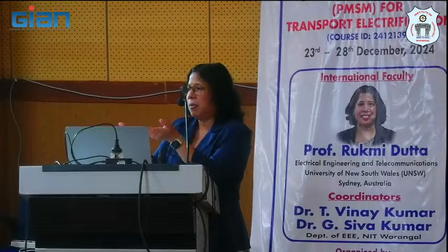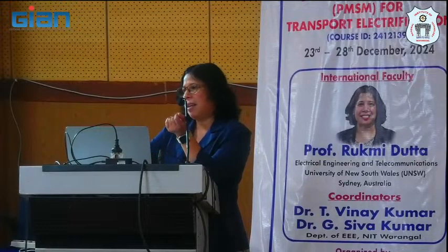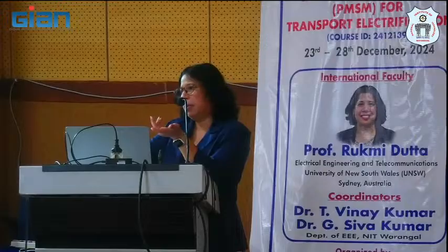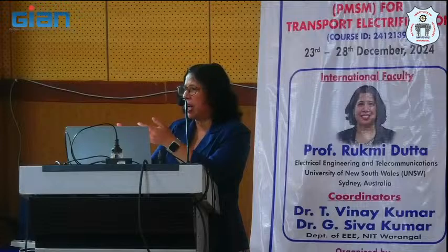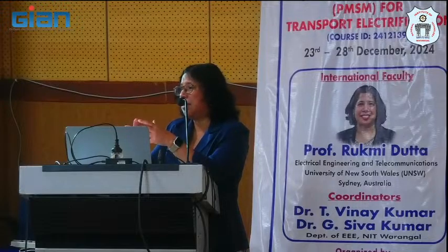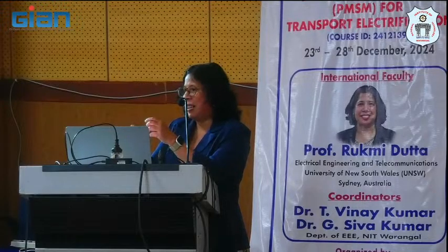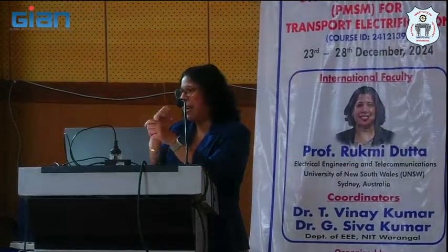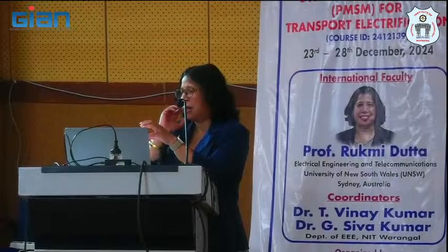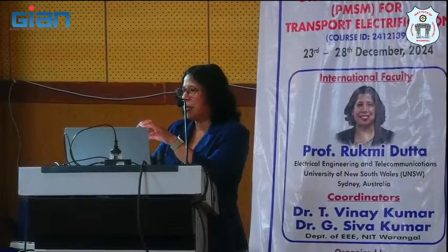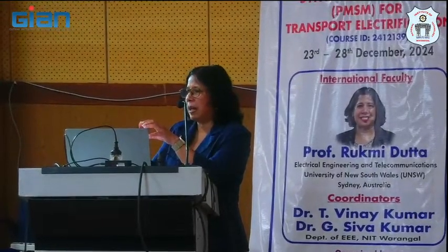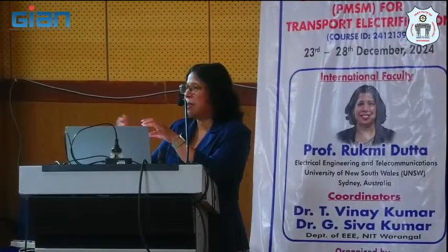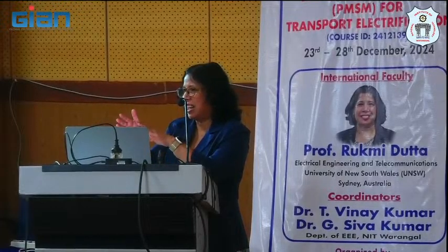So for that we actually use I/F. We could do V/F, but we did I/F because I/F is a little bit more accurate, or you have a little bit more control because you are injecting current rather than voltage, so you have the control on your current. If we don't control the current for a magnet motor, it's also risky whether it is going to demagnetization if you push too much current, right?